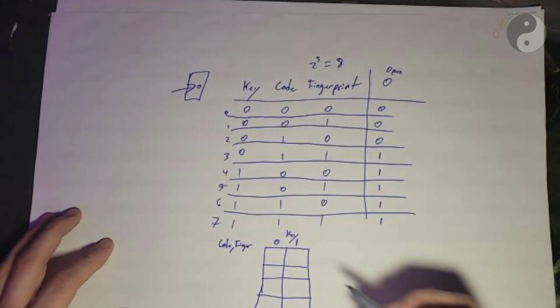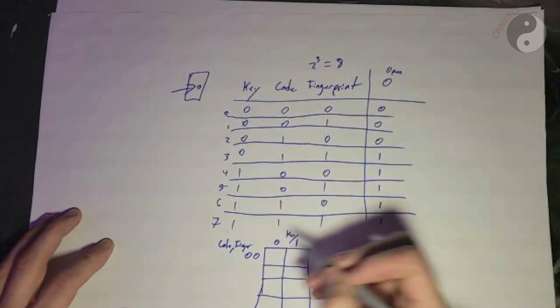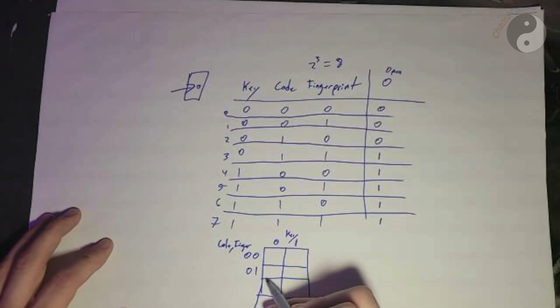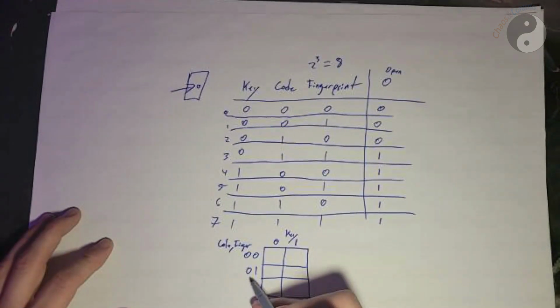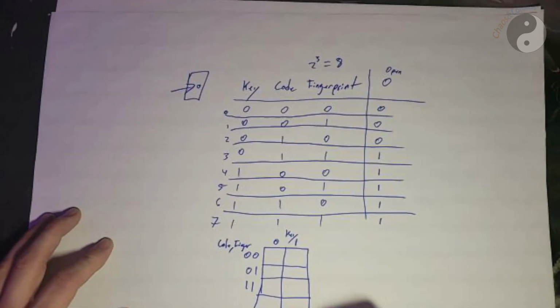And over here, we're going to fill it in with what is called gray code. And gray code just means that I can only change 1 bit at a time. So even though the next counting number would be 1, 0, so we can go 0, 1, 2, in gray code, we would do 1, 1, so that the only bit we flipped was this one.